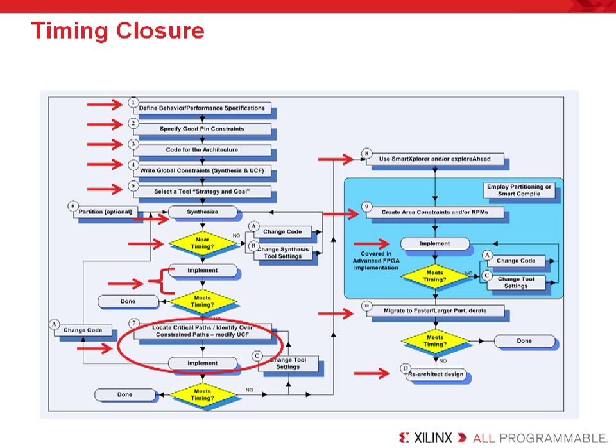Well, when we talk about performance, we're really talking about how your internal logic will map to the CLB resources, that is, the LUTs and registers. For the sake of discussion, we're not concerned about block RAMs, DSP slices, or dedicated processors or gigabit transceivers. We kind of figure that's a high-end functionality that you're going to choose a device because that device has those resources. But what we're talking about is how you get your generic HDL code, which will end up synthesizing and mapping to LUTs and registers, and then get that design to meet your system timing needs. That's really most often your timing critical path. It's seldom ever in dedicated hardware.